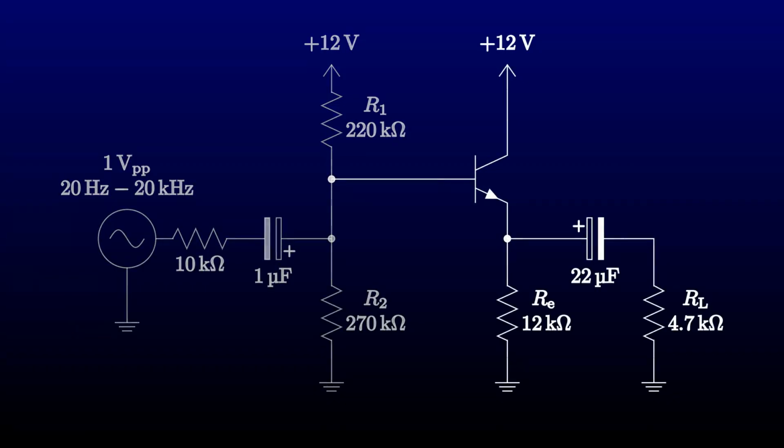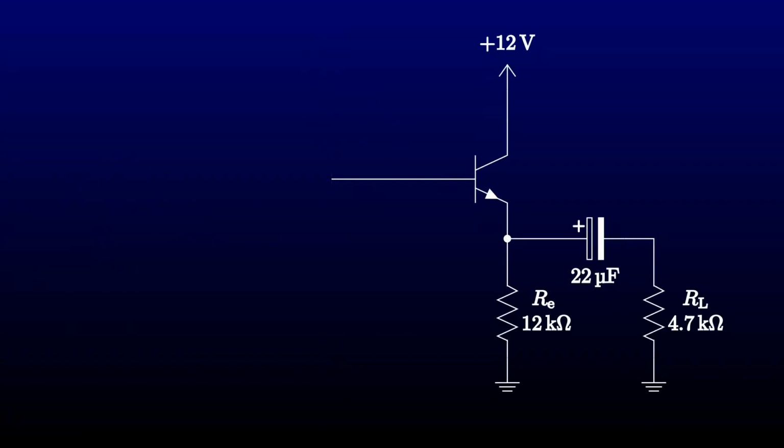Let's look at the choices we've made for the output circuit. Our problem is that we began by setting the emitter bias halfway between the power rails. To get the maximum possible output swing, it needs to be halfway between the maximum and minimum possible values it can have, and the minimum is nowhere near the lower power rail. But what's the value of that minimum? It turns out that it interacts with the value we've chosen for the emitter resistor, and that was determined by quiescent current. So maybe quiescent current wasn't arbitrary after all.